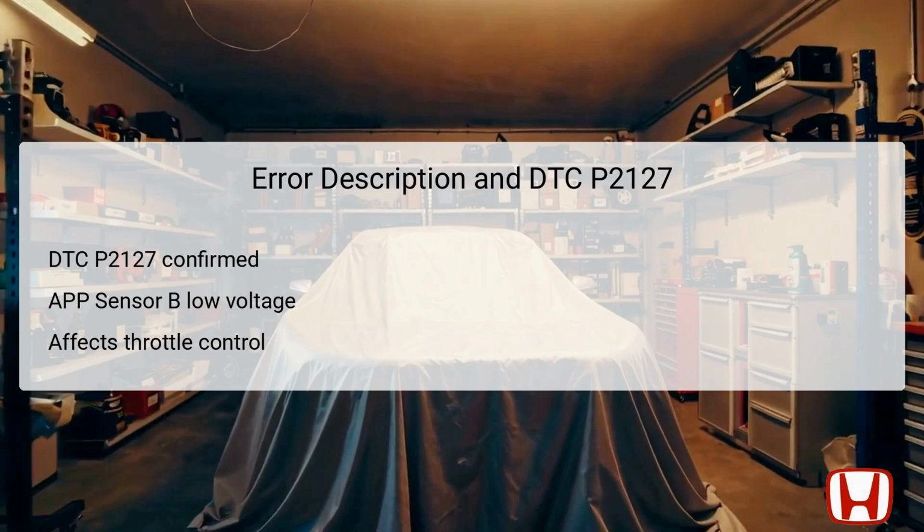The APP sensor is crucial because it directly impacts the vehicle's ability to accelerate smoothly, and any malfunction can impact engine performance and safety. In terms of electrical specifications, the APP sensor should typically output a voltage higher than 0.2 volts when functioning correctly. Intermittent low-voltage readings may signify problems with wire connections, damaged wires, or a defective PCM. Accurate diagnosis is paramount for restoring proper vehicle function.